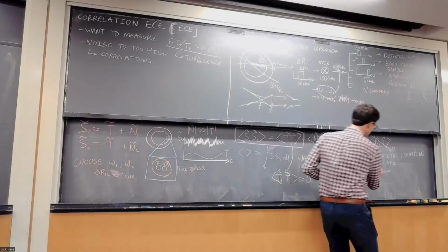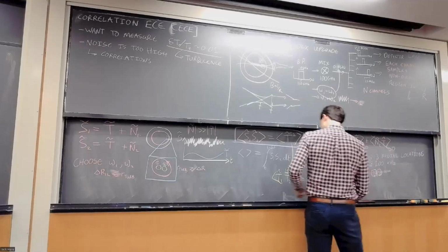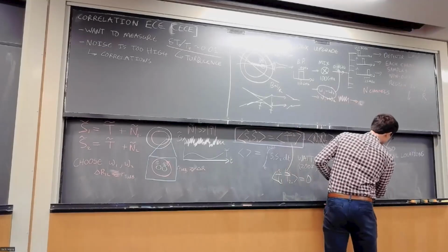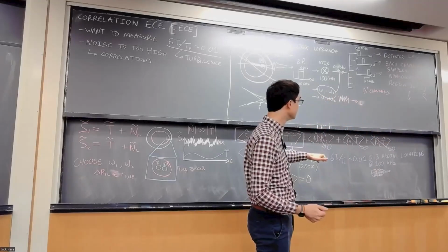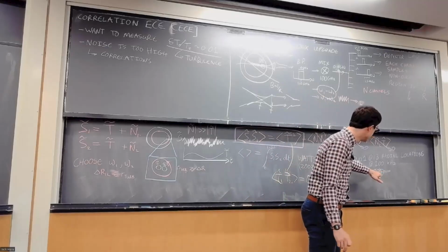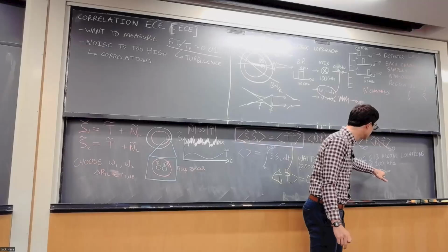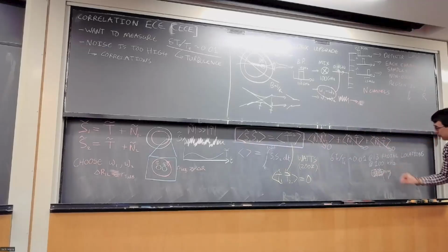Yeah, so the idea here is that there are eddies like this, or maybe at some other point there is an eddy like this. And so it will depend a little bit on how you do your time integration step here. This is part of the art of it, as far as I understand: you need to pick pairs because they're the only ones that could possibly be close enough to correlate. If you try and pick this one and this one, it will go to 0. But as well, the eddies are going to be moving in time. So you may end up with a situation where at some point your eddy has moved across and these two are no longer correlated because the next two are correlated.